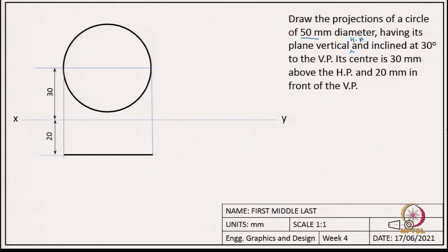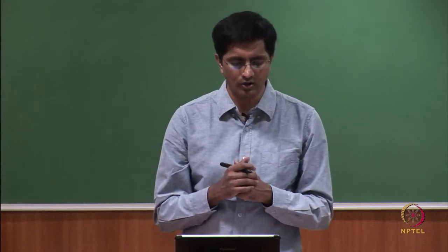Once done with the first step, we have a few more things to do at this step, because to help us draw the ellipse, we want to divide this circle into 12 equal parts. It need not be 12, it can be 24 or 8 or some other number, but 12 is a balance of not too many or not too few.